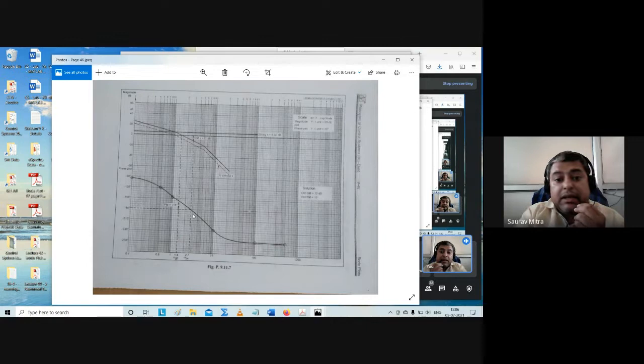That means there will be a frequency at which the phase will cross the minus 180 line. And how much is that frequency? It is given here. It is called omega PC. Omega PC is equal to 2.7. So these 2 frequencies you have to put. At least this frequency omega GC you can put in the phase plot, and you can find that the phase will be minus 165 degrees at omega GC equal to 1.4 radian per second. So I'm first telling you the answer, because whatever I do, if you are not drawing it, there is no point explaining any of these things.